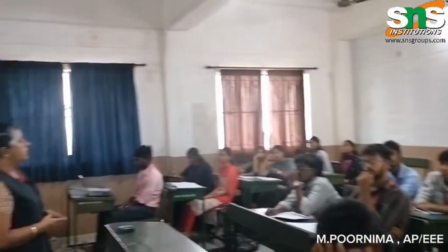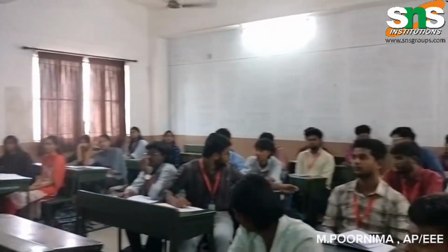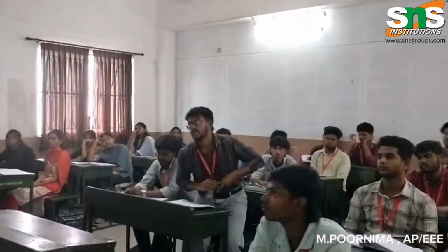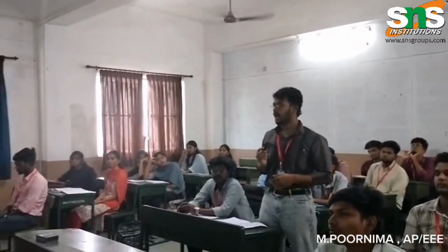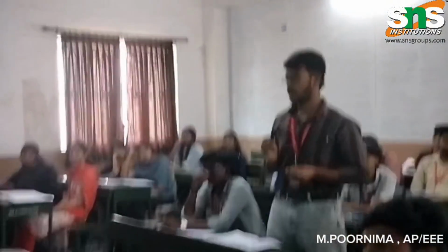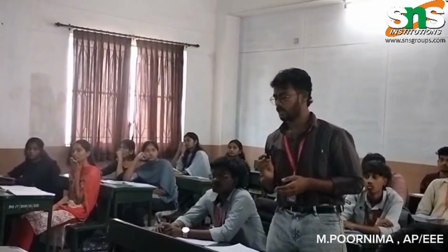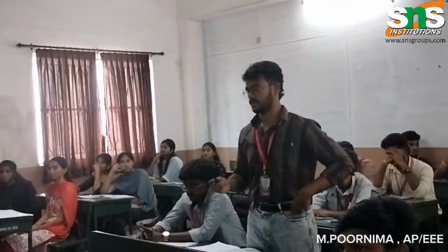Any comparison between earthing and grounding? Can anyone say about the comparison? Then we can implement the stages: soil resistivity testing, step and touch potential limits, ground resistance less than 1 ohm. Next, electrode selection. Next, periodic maintenance records. So these are the steps.